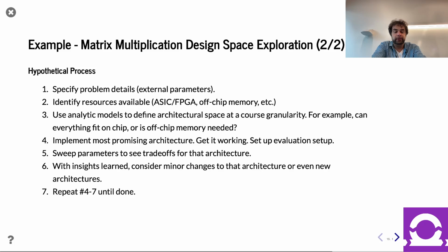This is the part where having an agile development flow and having generators really pays off, right? If you only get to go through this loop once, you can see there wasn't a lot of early-on planning, right? So the chances that this design is exactly the right design are not that high, right? A waterfall approach would probably try really hard to have a good plan in advance, but I'm telling you from experience that you can't always know in advance, right? You don't know how big certain things are going to be. Trust me, you want to instead keep revising at the back half of this.